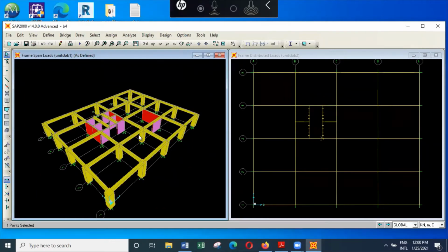And one of the important pieces of information that you need to find the natural period of vibration is the mass of the structure, not the weight of the structure. It's the mass of the structure. So we can easily get the mass correct if we represent all the elements with the correct dimensions.